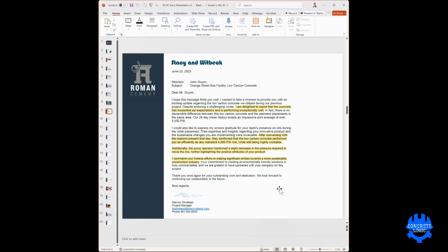It does say in paragraph 1 that the average strength was 5450 psi. One of the trucks came in at about 6,400 psi at 28 days, which was incredible. Another one came in lower, and that was kind of the anomaly. So we just took the average between the highest and the lowest, and it came up to 5,540 at 28 days, and it was over 6,000 at 56. So we got great strength, great workability, and this saved about $5 to $6 per cubic yard, reduced the amount of cement by about 100 pounds per cubic yard.